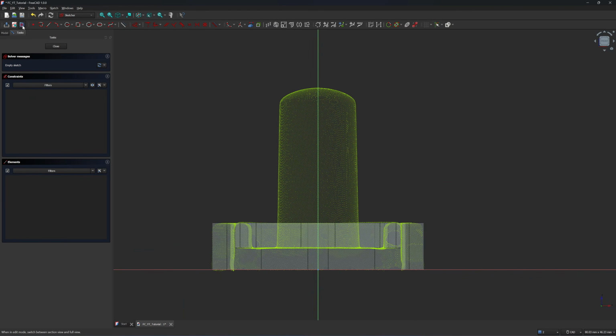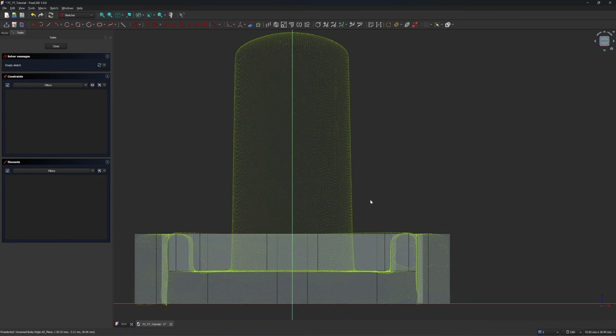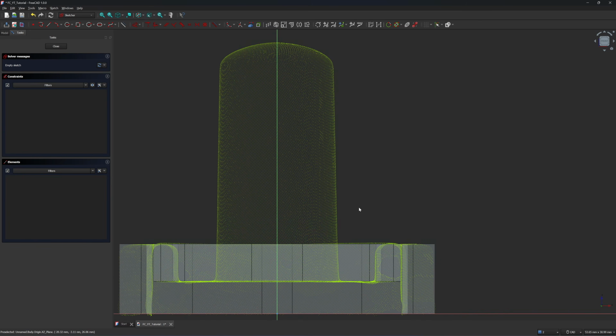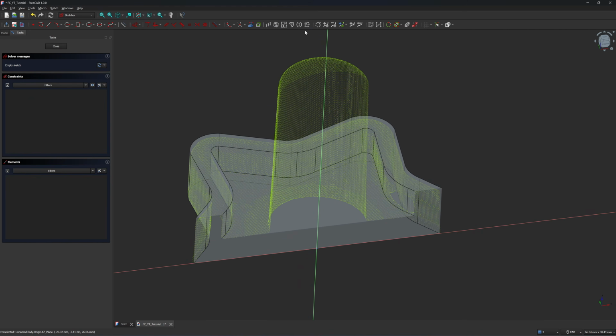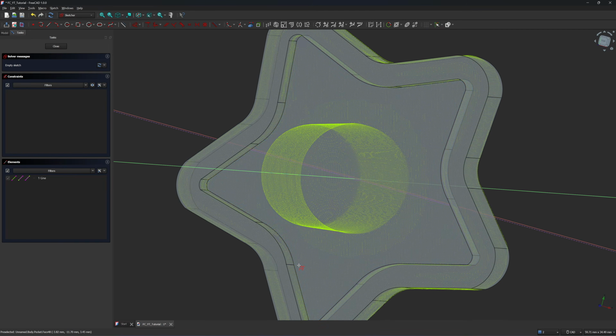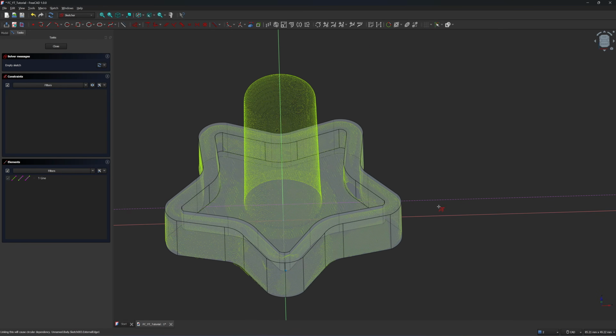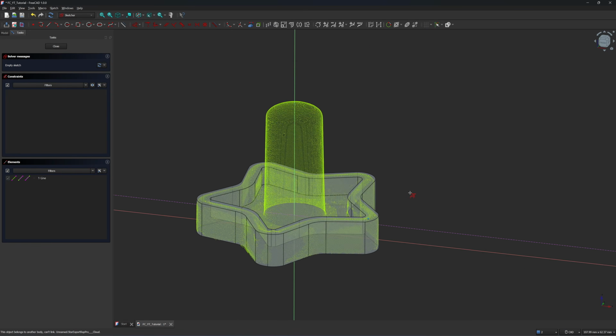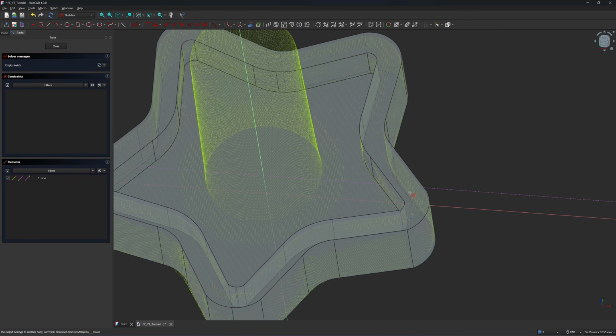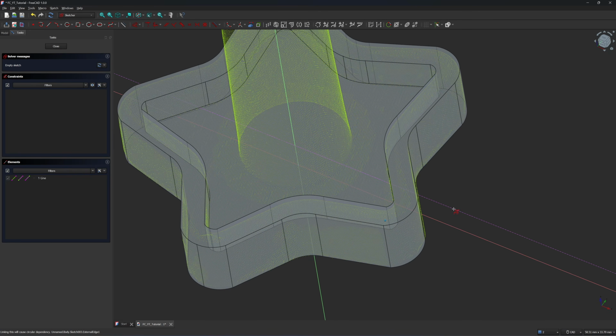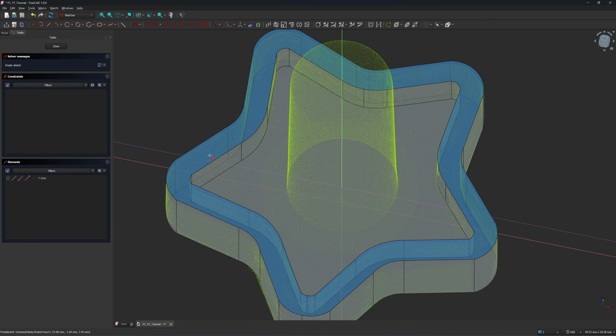And then you can do a sketch cutting. This button here will make a section cutting of the sketch. And next I'm going to project. You can use this button here. It will project the plane onto the sketch. Okay, all right. So see the line here. It's quite difficult to click, probably a bug of the software, but it works finally. And this magenta line here is a project line.